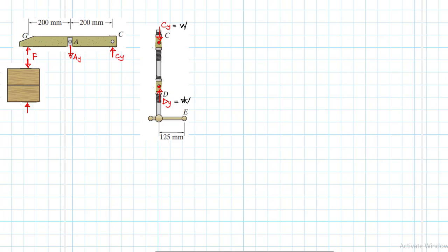Because we have two W's, and the nut at D is interacting with the threads at D and the nut at C with the threads at C, and there is friction between the threads and the nuts, we expect friction. To overcome that friction we need a certain magnitude of moment.